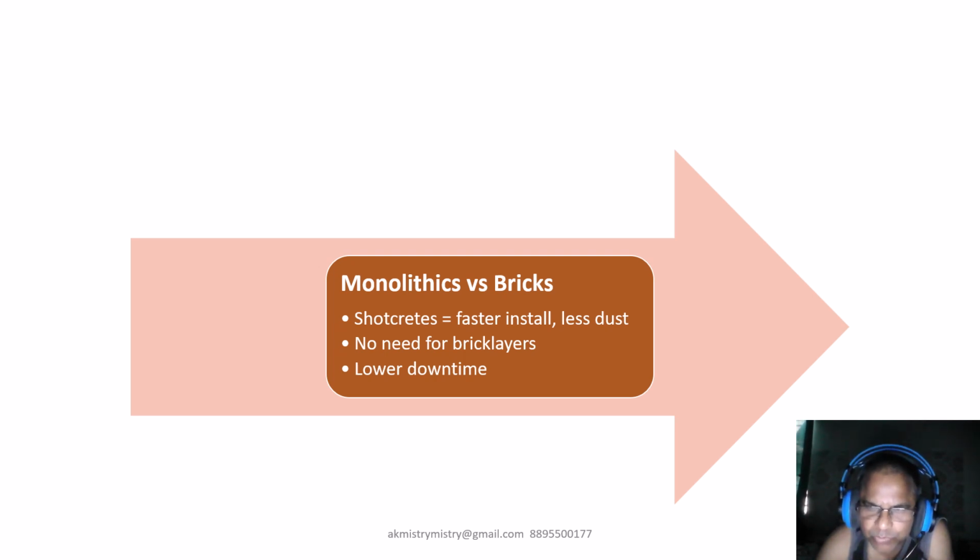One more important thing is that shotcrete is also a much faster way to install, and it is a sort of monolithic single-piece fabrication, not like a brick where we have a lot of joints.